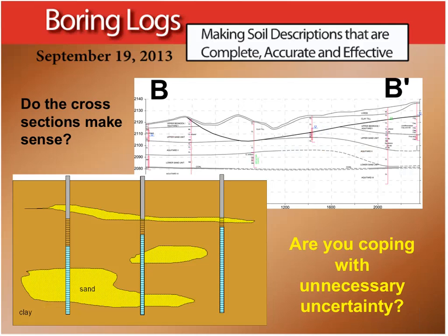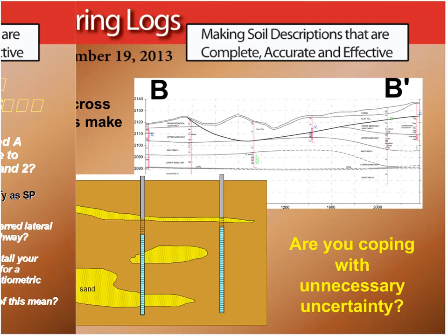How many times have you reviewed boring logs containing virtually no meaningful information about the geology? Maybe they lend little or no clues about how subsurface units or physical properties correlate, plus perhaps the lack of standardized information calls their credibility into question. Then where are we when we find our monitoring wells have virtually no basis for either vertical or lateral placement, and we discover we're coping with appreciable and unnecessary uncertainty at our site?